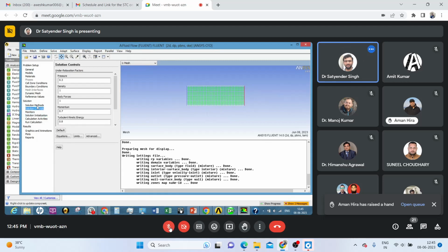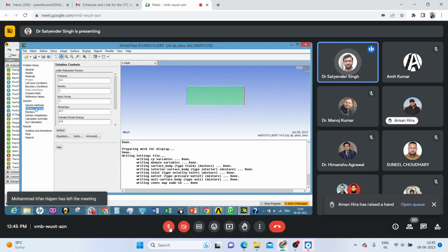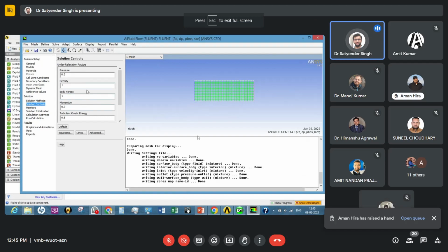And in the method, pressure standard, okay, that is fine. Here it will consider some under-relaxation factor. That is the pressure projection approach, where pressure will be calculated. There will be a weightage to the velocities at the previous time level, and accordingly we will get some value of the pressure in the pressure projection method, and the Poisson equation is generally used there.